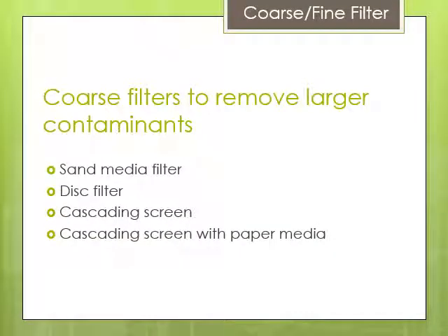All right, coarse filters. Let's talk a little bit about that. These are to remove large contaminants. So the common ones are sand media filters. This is sort of what you see in a pool. Disc filters, cascading screens, and cascading screens with paper media. We'll go through them all, and I'll tell you right now that this one here is probably one of the most common in the ornamental world. And I think I've seen it in a number of commercial veggie houses as well.